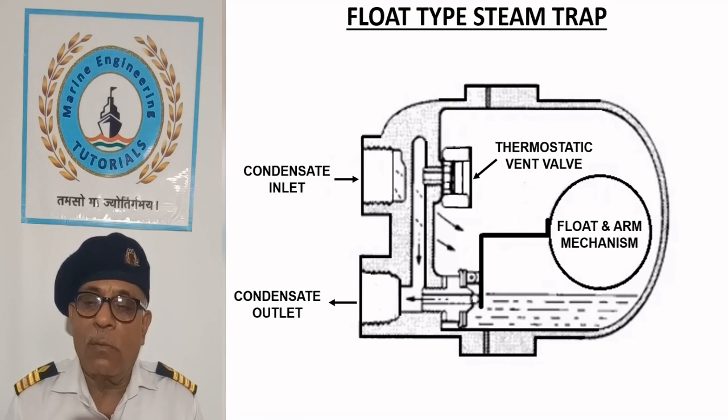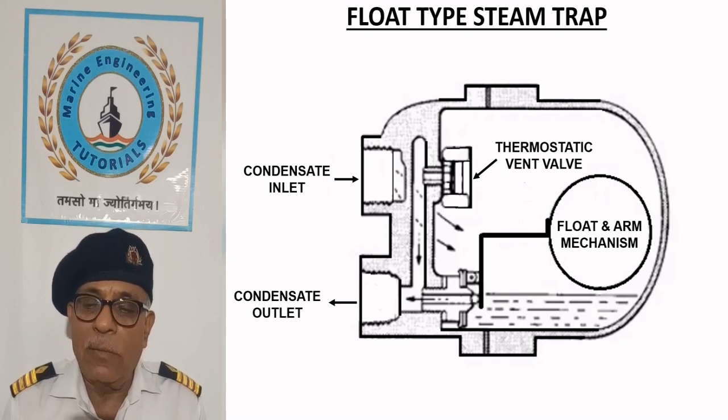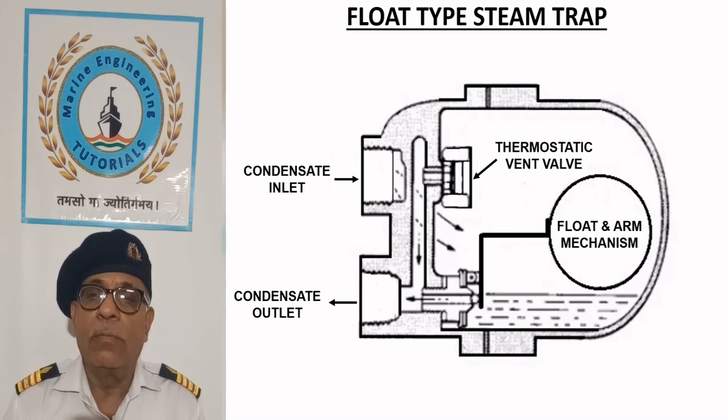As the discharge valve is below the water line, it employs a venting system to discharge non-condensable gases through a thermostatic element which opens the valve when cooler non-condensable gases are present but closes the valve in the presence of hotter steam.